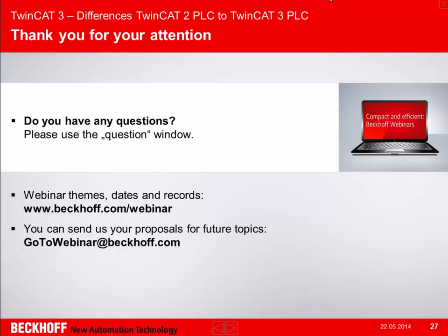The question is what platforms we support with TwinCAT 3 PLC. We support, of course, the x86 platforms for XP, Windows 7, Windows 8, Windows 8.1, but we support also CE, but not on all platforms. We support CE in the moment only on the CX9020.